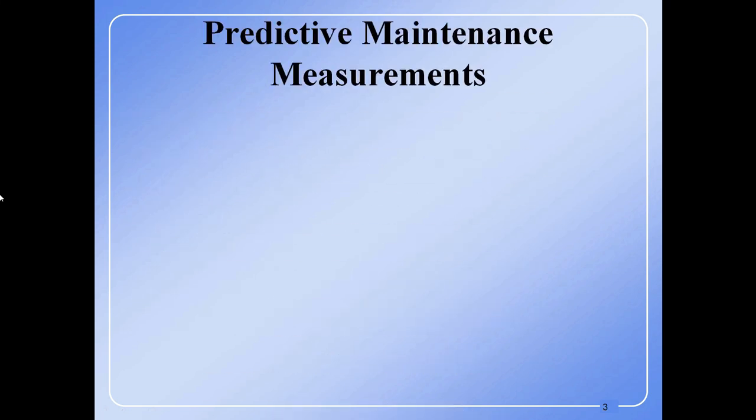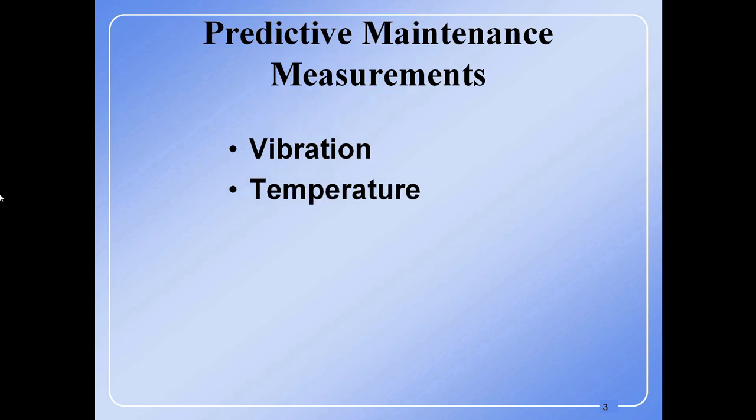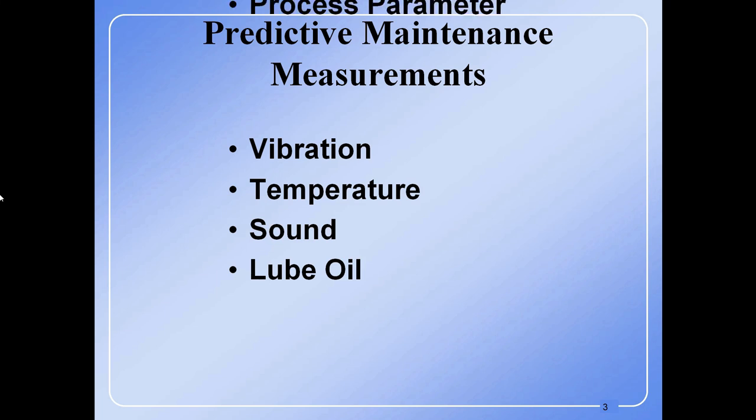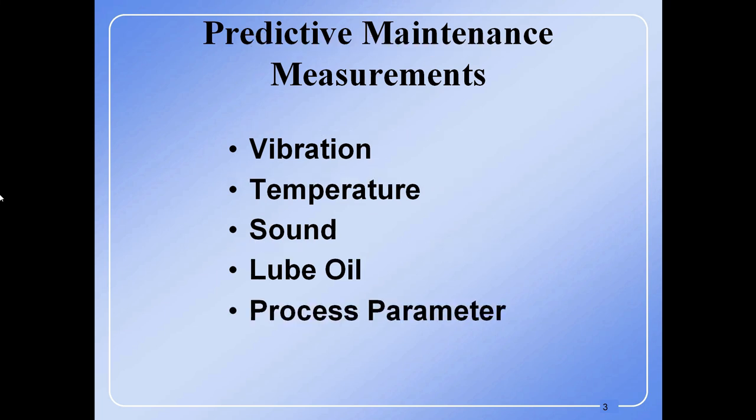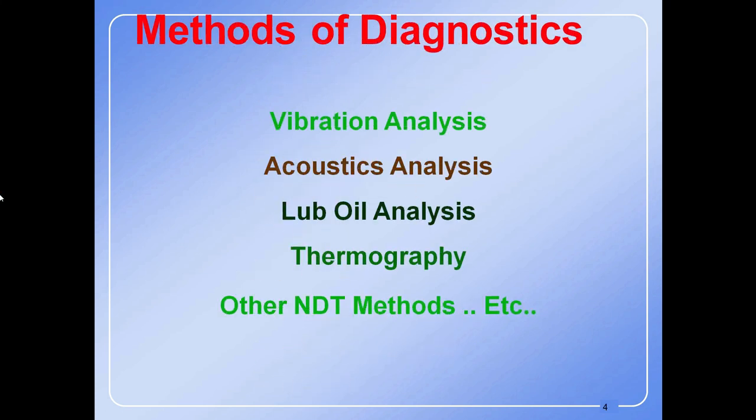Predictive maintenance measurements: vibration, temperature, sound, lubrication oil, process parameters, pressure, flow, and speed. Methods of diagnostics: vibration analysis, acoustic analysis, lubrication oil analysis, thermography, other NDT methods, etc.